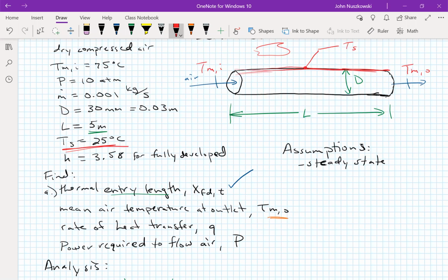So they're just telling us the surface temperature is constant, but this would be a situation where there's a fluid on the outside that's condensing or boiling, right? If you had boiling water on the outside of the tube, it would hold the temperature to 100 degrees Celsius, because that's the temperature of boiling water. So that would hold that boundary at constant temperature. Same with condensing, same idea there, okay?